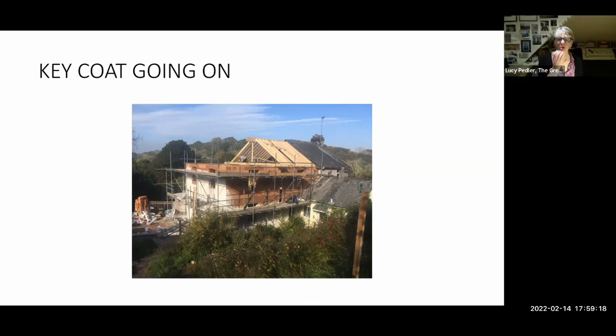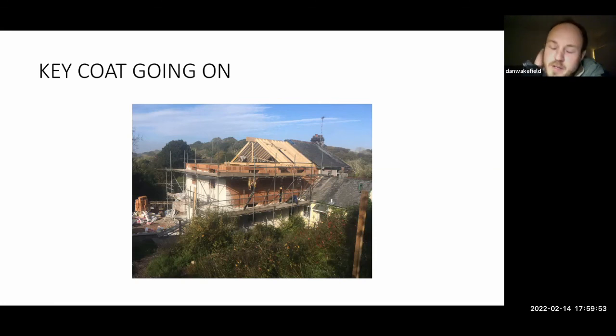So there was a comment from Joe, in an effort to avoid excess concrete, and we all know there's a huge amount of embodied energy in concrete due to the cement. We're considering using glulam for lintels instead of the proprietary lintels. The manufacturers are happy with this, but from a buildability perspective, does Dan have any concerns about this method? And actually, Jenny then commented that she'd be concerned to combine timber in case it stays damp. So, you know, that is a risk. I think it'd be interesting.